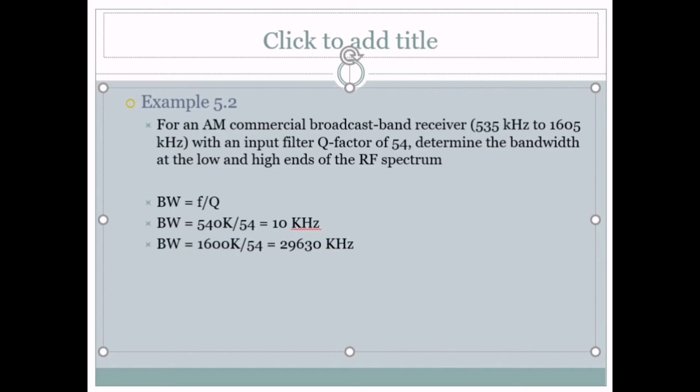So why do we start at 540 rather than 535? Because the 5 kilohertz is used as the guard band of the AM frequency.